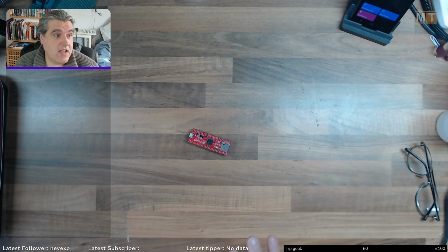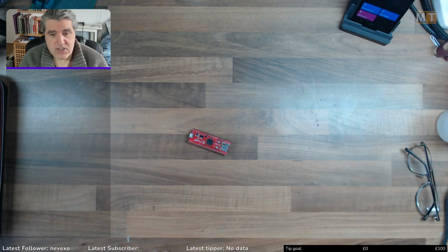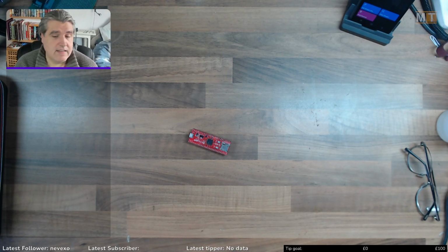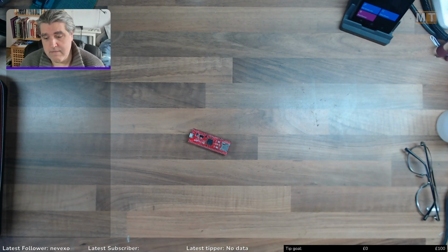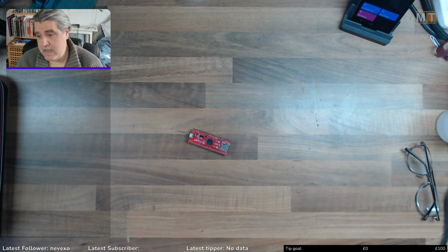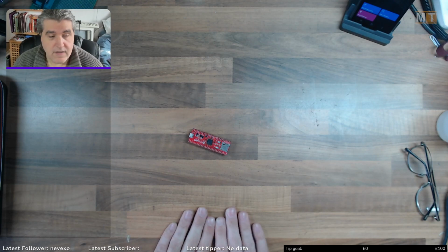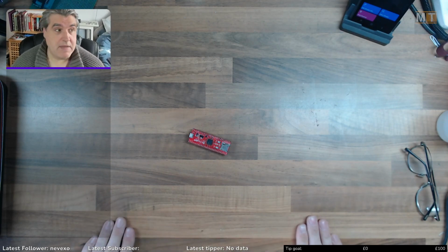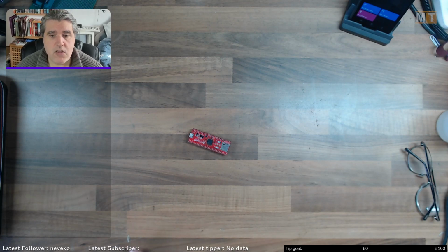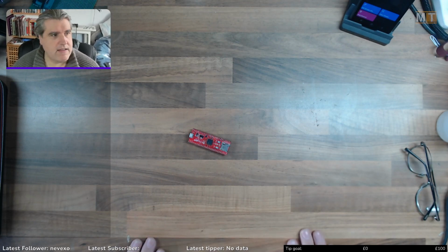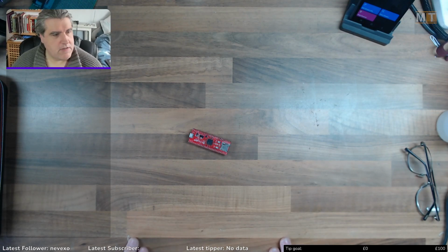Of course, there's no standard microprocessor bus, so I would need to have some way of changing the personality. So it could be an 8080 bus, a Z80 bus, a 6800 bus, a 6502 bus. The idea, though, is that it'll only be an 8-bit bus, with possibly a few address pins so that I've got a range of addresses that I could read or write from. That's the way I'm thinking of doing it.